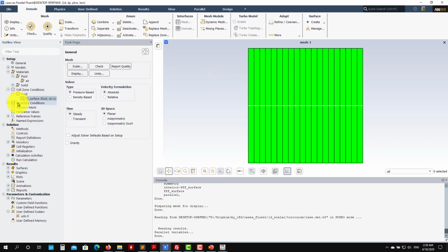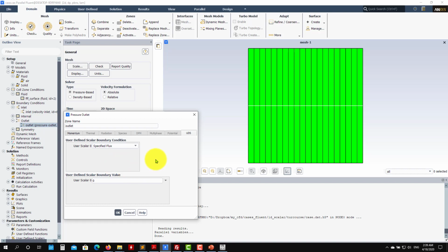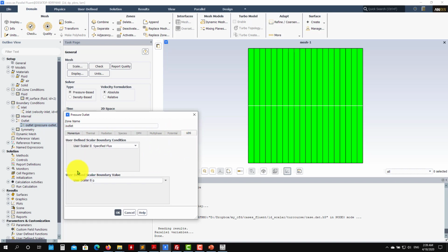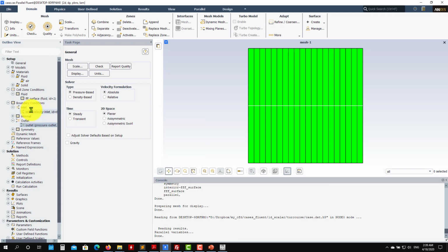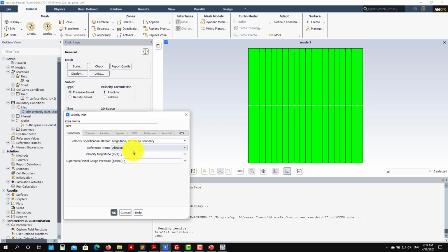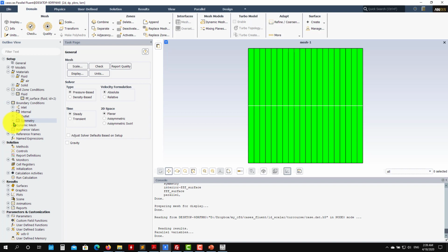We have it there. Then we go to boundary conditions. For the outlet, we have normal outlet pressure, the momentum here, and then the UDS, put it to 0, specify flux, which is the Neumann. For the inlet, specify value is 0, specify flux is Neumann, and the momentum just give the velocity value, the one that we will convert. And then the rest are wall, symmetries as standard.